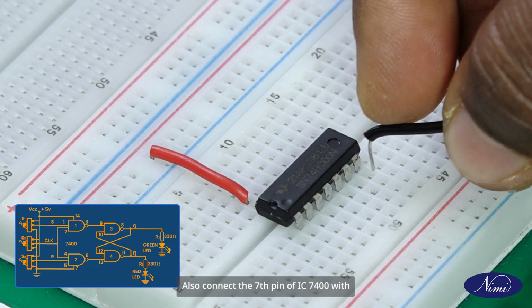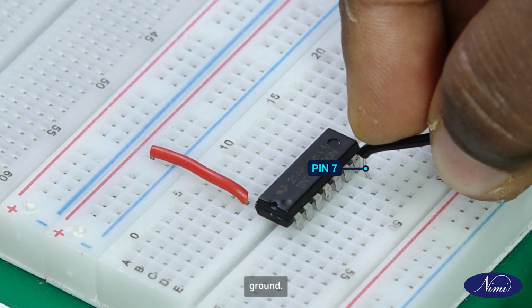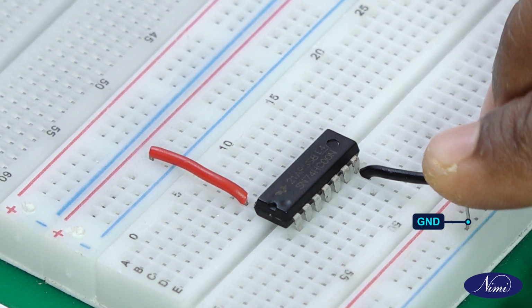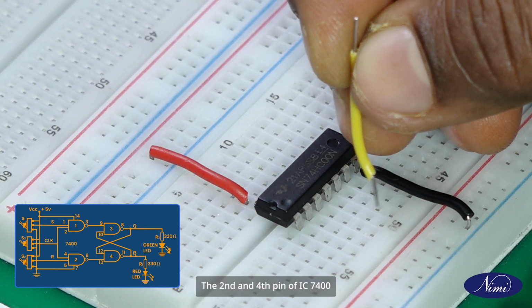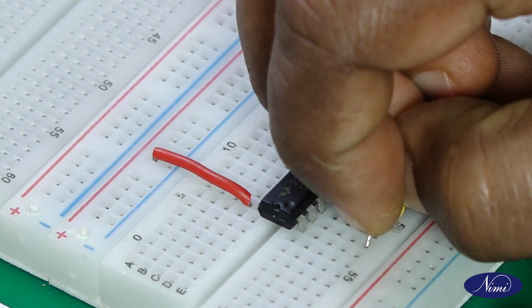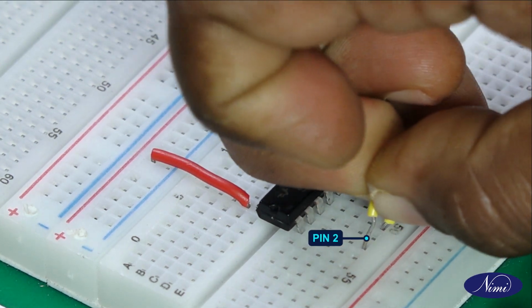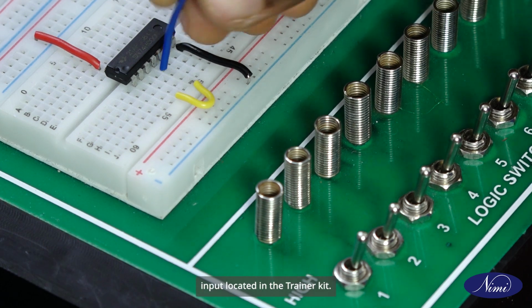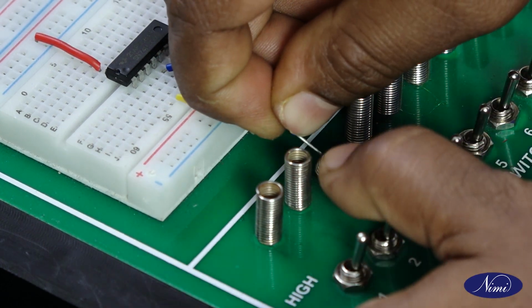Also connect the 7th pin of the IC 7400 with ground. The 2nd and 4th pin of IC 7400 are coupled together. This is connected to switch 3 with clock input located in the trainer kit.